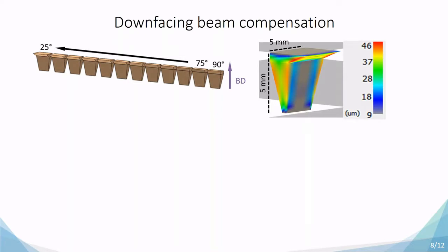A quick study on the residual stresses was also performed. This is a simulation tool within the 3D Expert tool provided by 3D Systems, so that we know that the deviation measured in these down-facing surfaces comes mainly from the down-facing region and not from shrinkage or residual stress phenomena, which are typical of the bulk of the part.